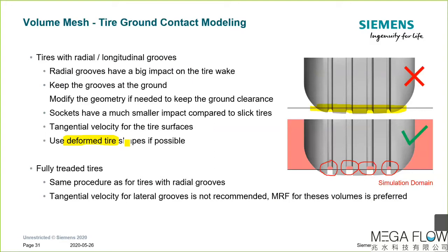When you have a fully treaded tire, the procedure is basically the same. Well, tangential velocity is actually not correct for lateral grooves. There are a couple of nice studies from Chalmers University in collaboration with Volvo. So for these grooves, the MRF approach is recommended.